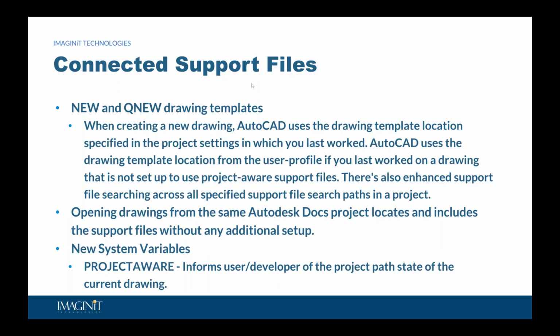So, NEW and QNEW drawing templates. If your drawing template is in Docs, you can actually tell it to use that. When creating a new drawing, AutoCAD uses the drawing template location specified in the project settings in which you last worked. AutoCAD uses the drawing template location from the user profile if you last worked on a drawing that's not set up to use project-aware support files.